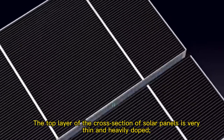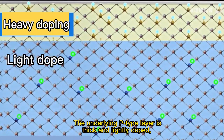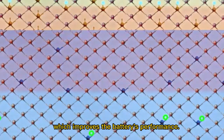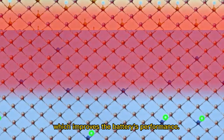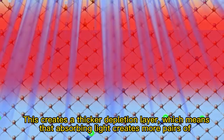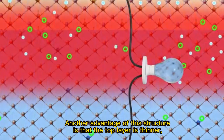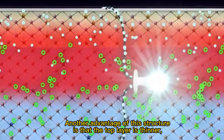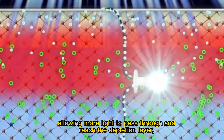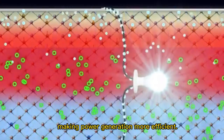The top layer of the cross-section of solar panels is very thin and heavily doped. The underlying p-type layer is thick and lightly doped, which improves the battery's performance. This creates a thicker depletion layer, which means that absorbing light creates more electron-hole pairs, and thus more current. Another advantage of this structure is that the top layer is thinner, allowing more light to pass through and reach the depletion layer, making power generation more efficient.